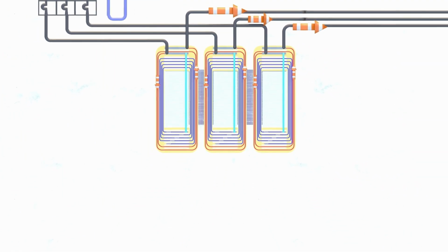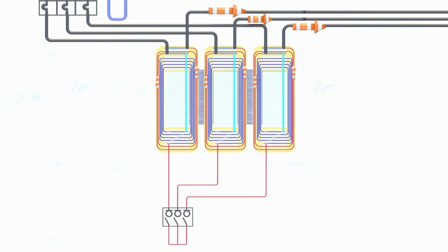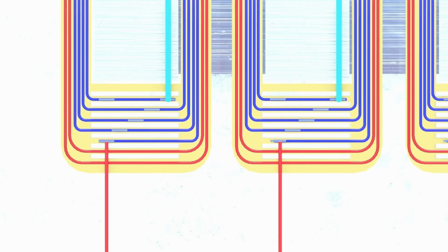Another vital modification to our efficiency filter is the establishment of an extra floating star point, which is implemented without a connection to a neutral conductor. The 3 secondary windings are combined in the floating star point via the external aluminum contacts. And here lies a crucial innovation leap of our efficiency filter. The floating star point is currently not connected to the neutral conductor and can therefore assume different potentials depending on the load, which result from different phase loads and the opposite winding direction.